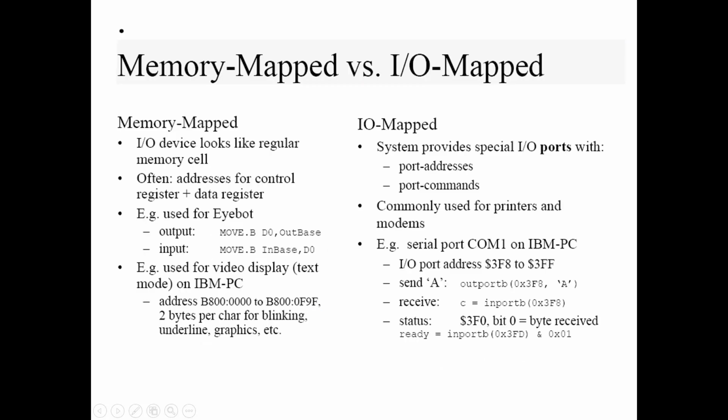Let's explore the different methods of implementing input and output devices in embedded systems. Number one, memory-mapped input-output, in which the same address space is shared between memory and input-output devices. Input-output devices are assigned specific memory addresses, and the CPU can read from and write to these addresses just like it does with regular memory.